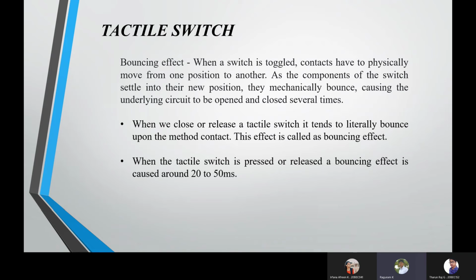To overcome this, we will use a concept called debouncing, which can be implemented in either a hardware or a software method. Using the software method, we will give a delay of 20 to 50 milliseconds to avoid such errors.